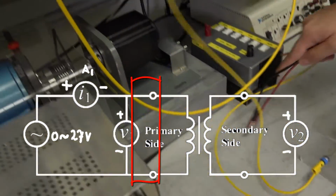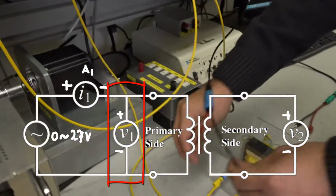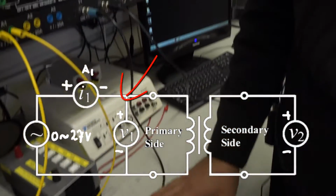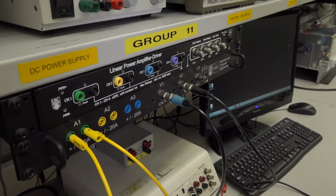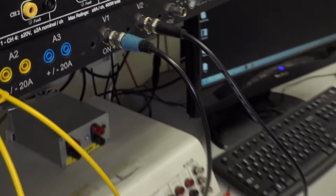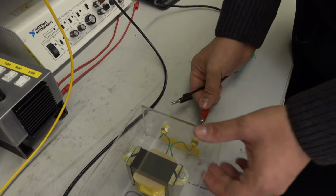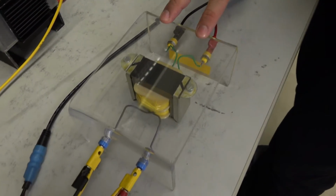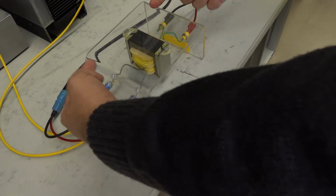Then you will need to connect your voltmeters as well to your transformer. Make sure that you connect the positive terminal of the voltmeter to the negative terminal of your current meter on the same side. Then you will need to connect your second voltmeter to the other side of the transformer, making sure that the polarities of your voltmeters match on both sides. So positive on this side, negative on that side.